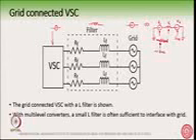There is also one more reason: if there is a short circuit here, the impedance X of that L filter controls the rate of rise of the current through the VSC. In order to limit that current, we put an X. So the L filter has two purposes. First, it allows us to exchange or control the power flow between the voltage source converter and the grid.